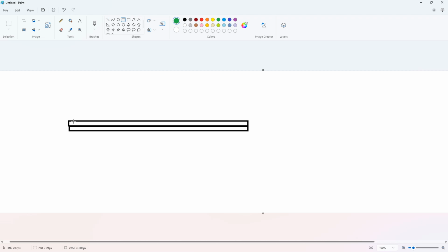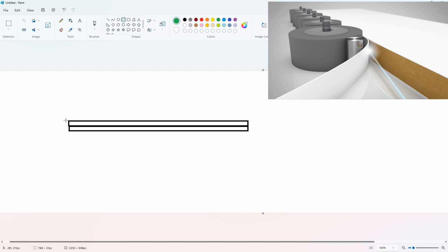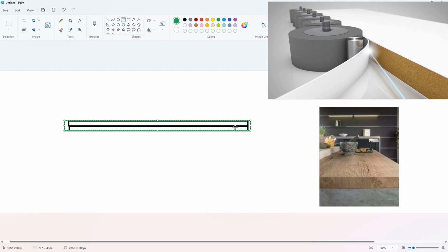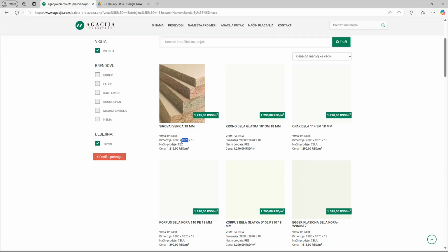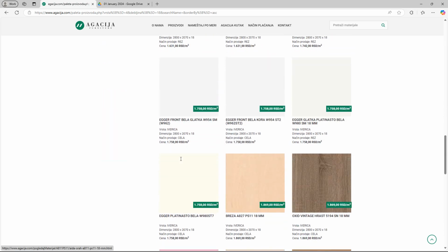And then, for example, if this is some wood design, you will also take this ABS edge tape, and then they will basically cover both pieces, so nobody will know that you did place 2 plywoods. It will not be visible, and in that way, now you are no longer limited by the width, because standard plywood table is 2.8 by 2.07, and raw plywood is very cheap.